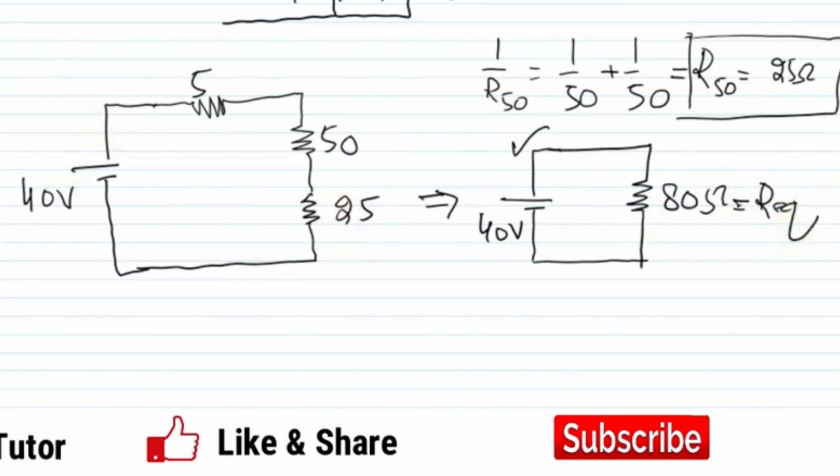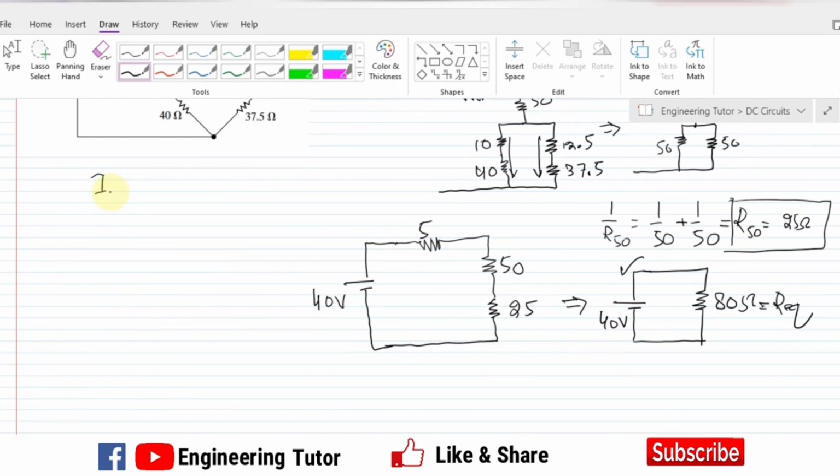Now we can easily find the value of current which is provided by the 40 volt source, by using Ohm's law. So I is equal to V by R. V is 40 divided by 80, so it is 0.5 amperes.